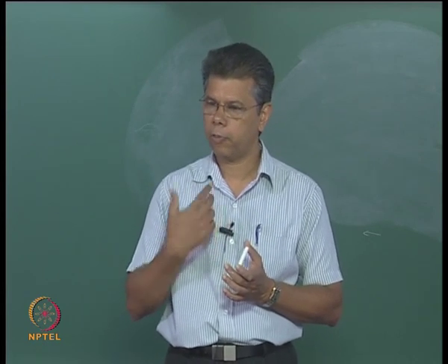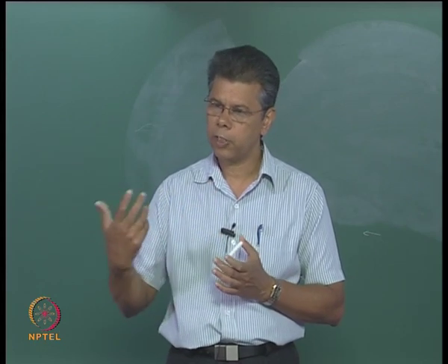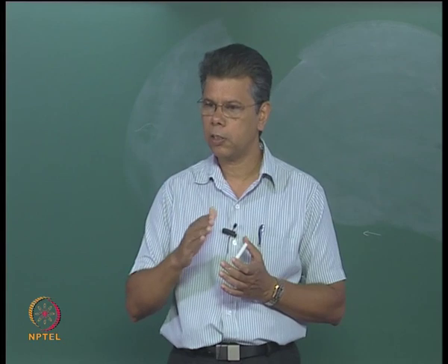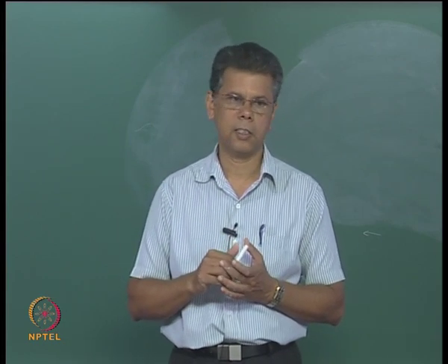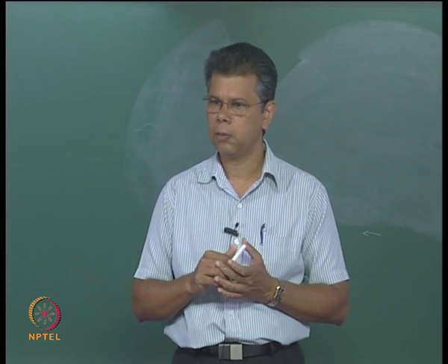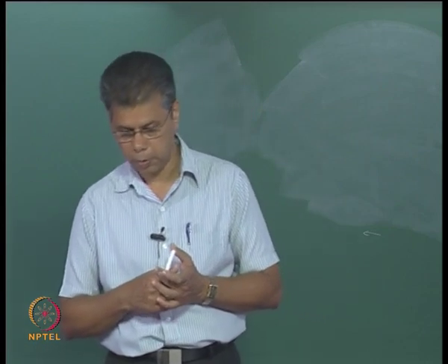So the roughness of a model and the roughness of a ship are totally different. The roughness increases in the case of the ship, and you have to increase the resistance estimated from the model to get an actual value for the ship which is in operation.